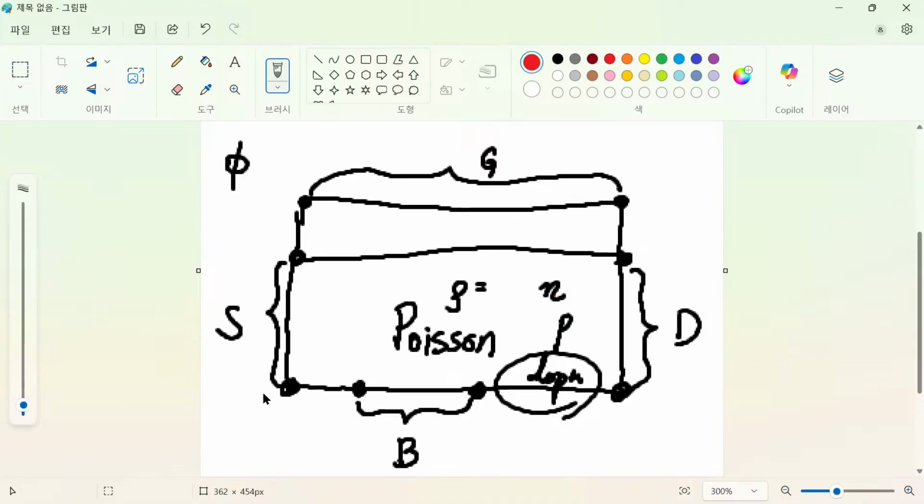We will assume the sub-threshold region. As much as we assume that bias condition, we can completely neglect the contribution from electrons. Wow! Then how about the hole contribution? The hole contribution should be considered.